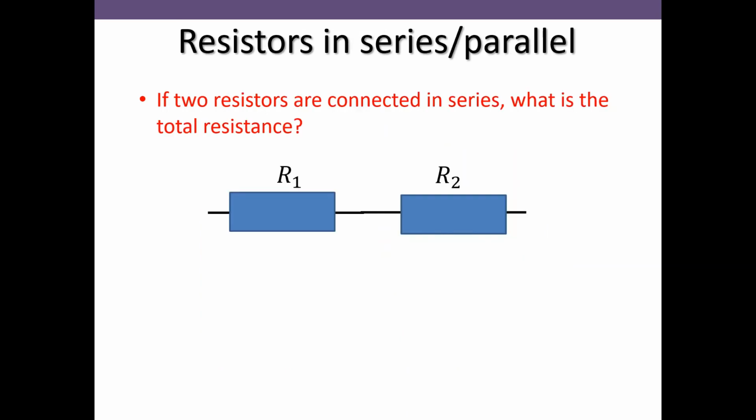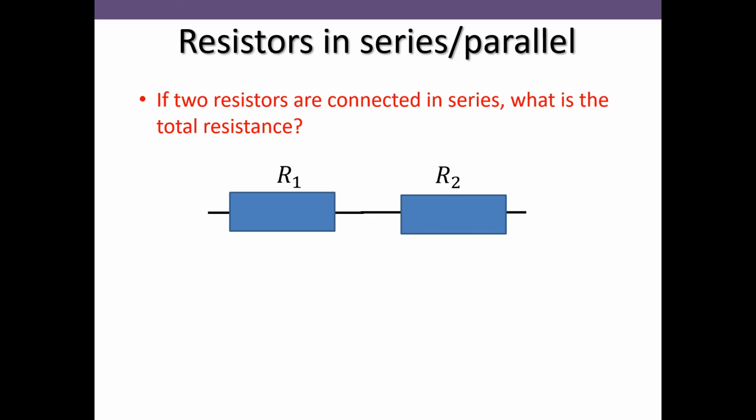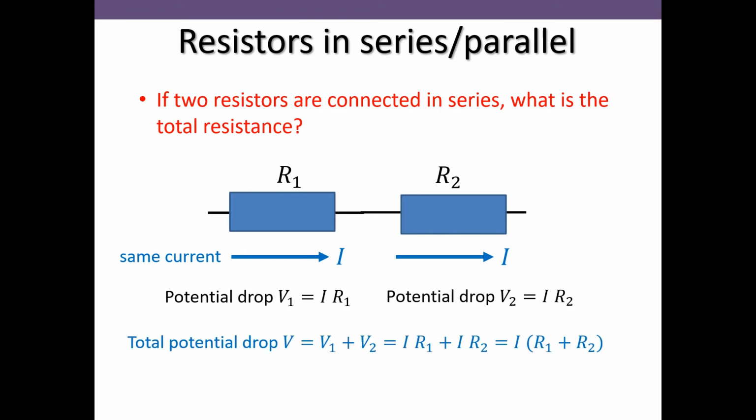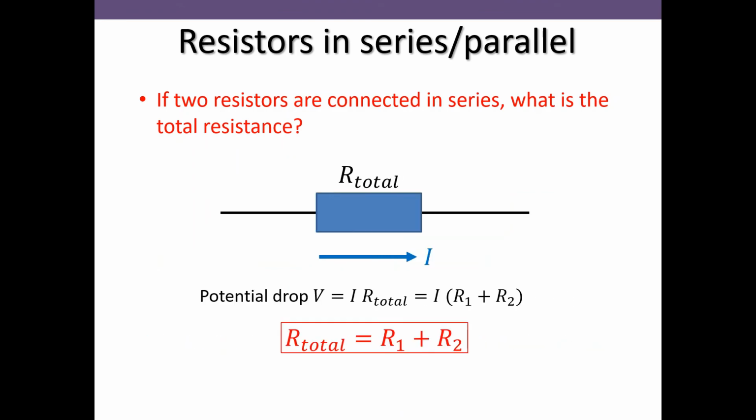Okay, so if you have two resistors in parallel, you just add them together. It's the total. I mean resistors in series, not parallel. Resistors in series. Think of them as turnstiles going into a supermarket, because they slow you down. When one turnstile goes after the other, it is cumulative, meaning the resistance adds on. So if you have two resistors in series, you add the resistances together.